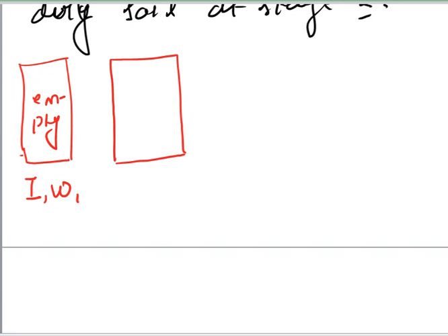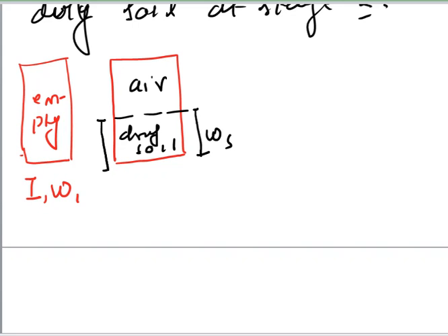having dry soil. So hence this is what it will be, air. Let this be the weight of solid and this is the volume of solid, and the weight at this stage is W2. Now the third pycnometer bottle will follow the same procedure.